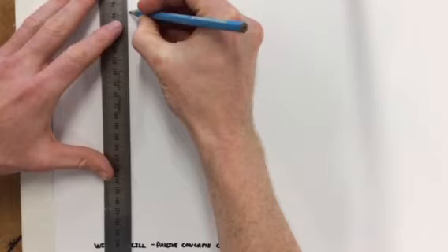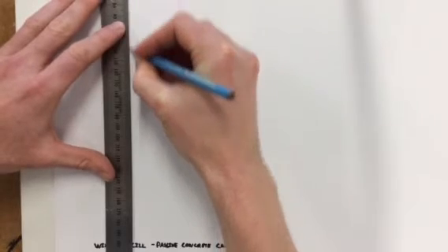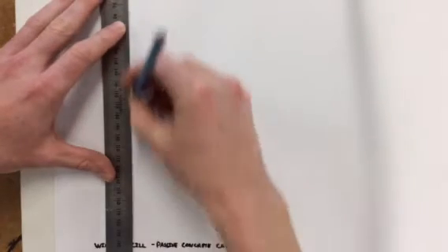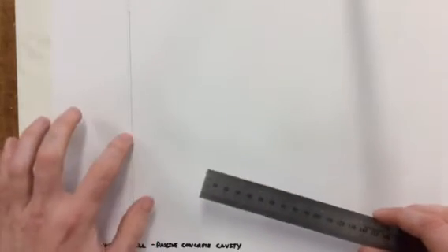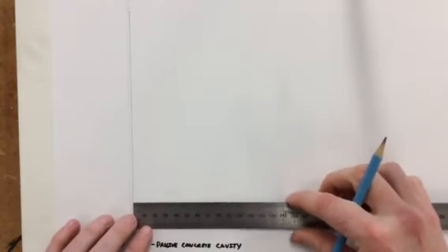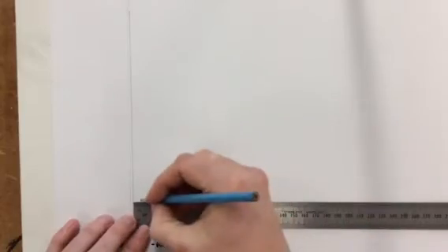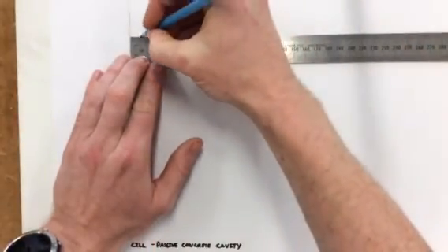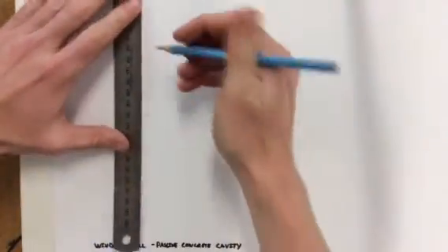Depending on the person doing it, I'm just leaving it as a 2mm gap. I marked it out twice there just to make sure my lines are going parallel. The last thing I want is them joining at the top. That's where the external render is. Then I'm going to come in 10mm, for the width of the block. I'm going to do the same up here again, just to try and keep me drawing straight.